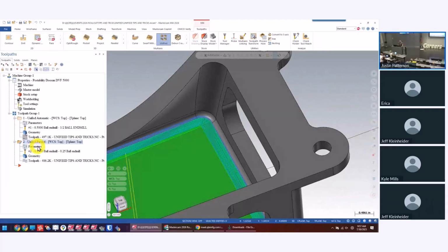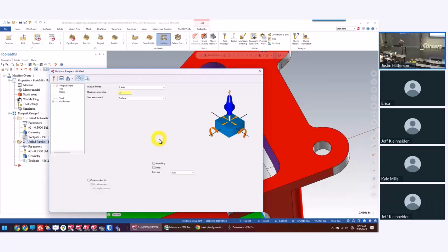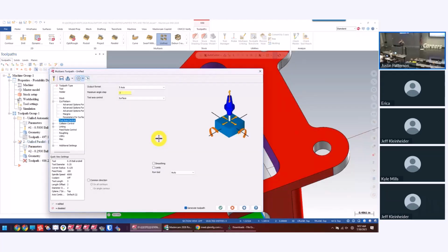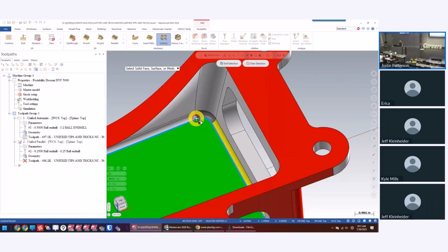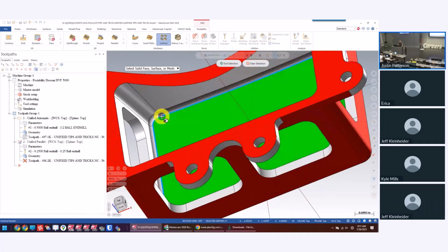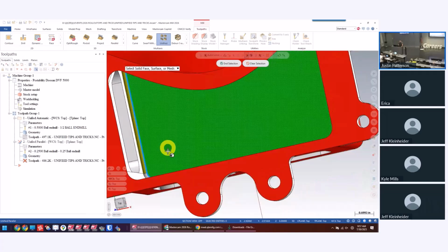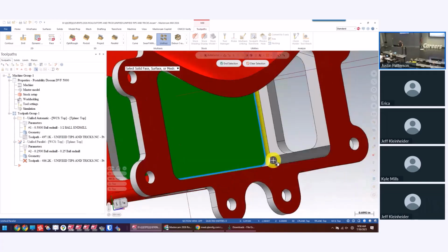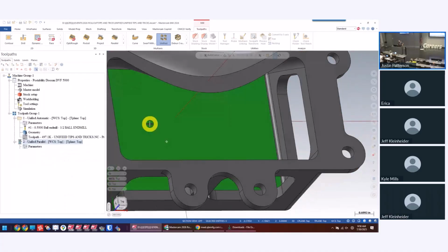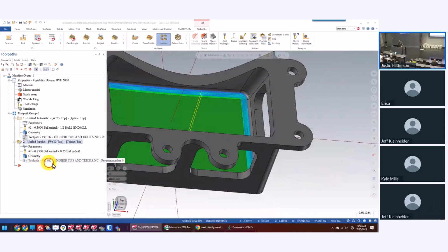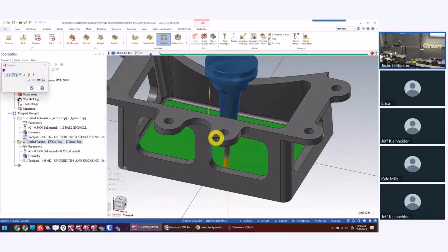I didn't have to do anything. But one thing I might change instead, because now I'm not worried about that tool hitting these top walls, right? I'm trying to blend that into that radius. So I'm going to change my collision control to be retract tool along tool axis if I come in contact with these radiuses. I probably could have kept the walls as well, but it's not the end of the world. Just like that. So now I'm forcing my hand. I'm not allowing my tool to violate that floor or that radius. We should blend really nice into that radius. And we still have the same tilt to avoid. We still have an awesome looking 5-axis toolpath.